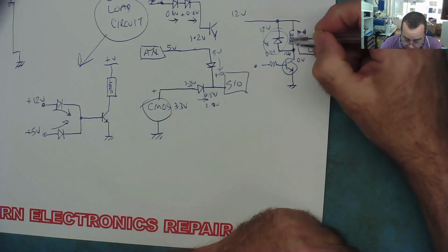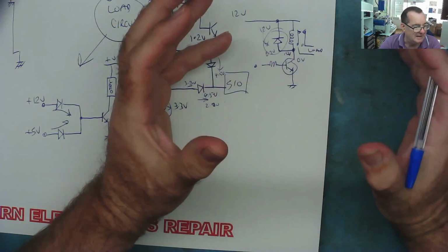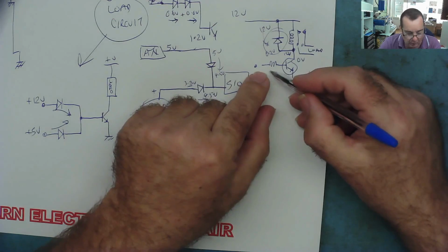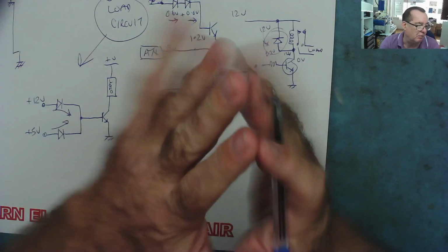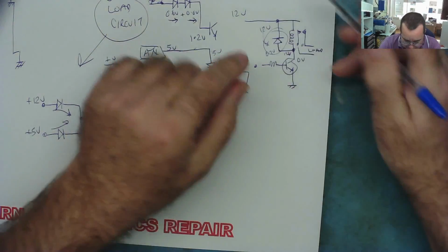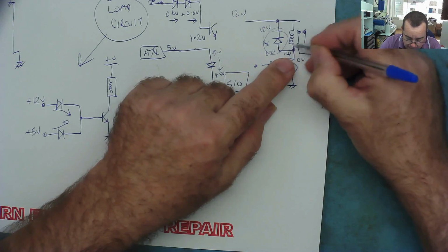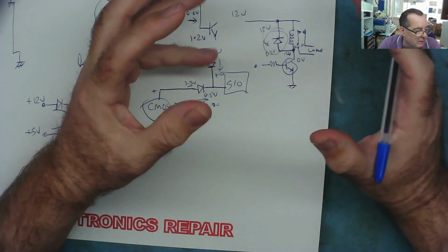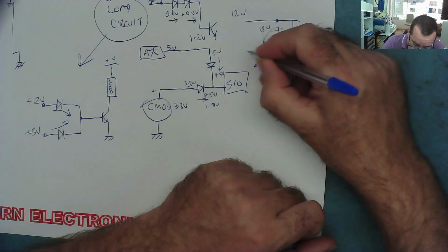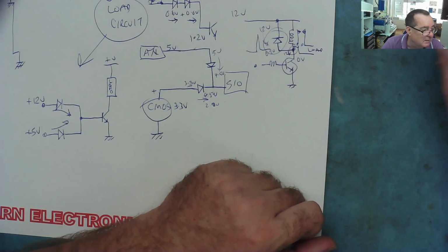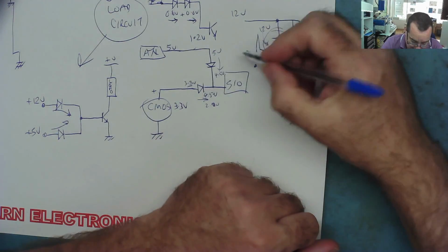When you pull the current through the relay, this inductor builds up a magnetic field, and it stores energy in the magnetic field. When you switch off, and this transistor suddenly switches off, the magnetic field collapses. The relay contacts open, the field collapses, and by doing so, it generates a large positive voltage on here. All the electricity stored in the magnetic field now comes out of the magnetic field. It's got to go somewhere. So it causes a very large voltage spike on this end. It suddenly spikes up, until this magnetic field completely collapses and it goes back down to 0 again.